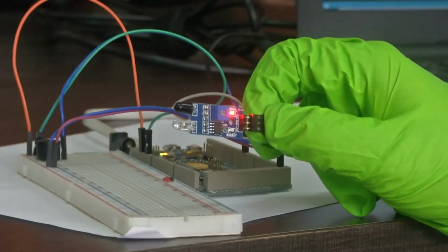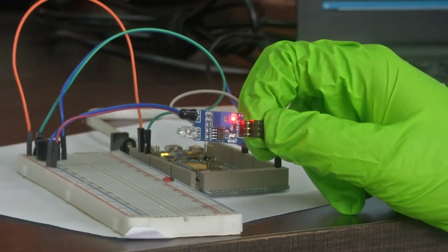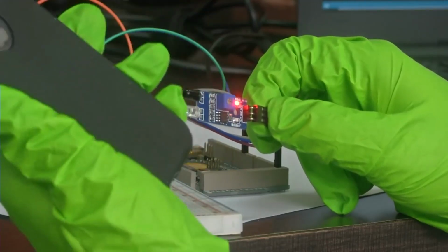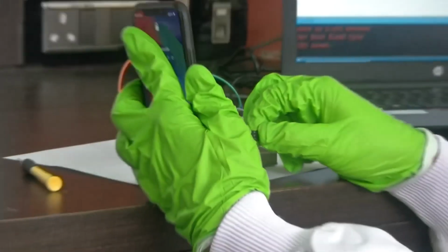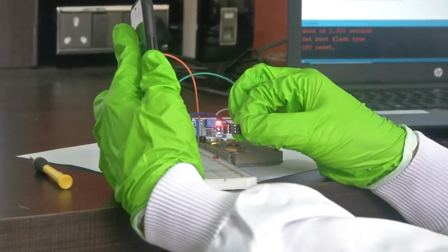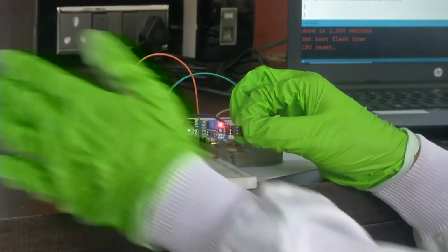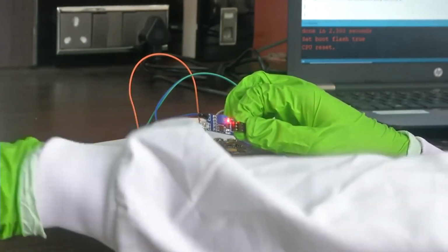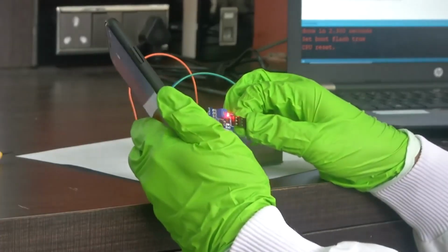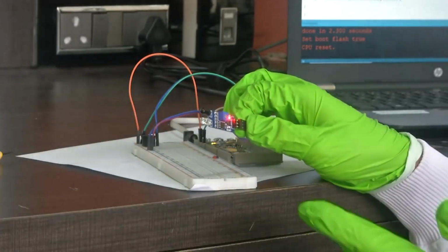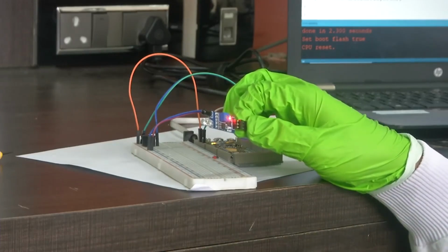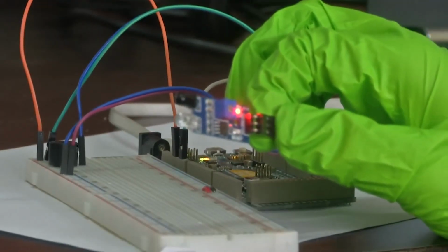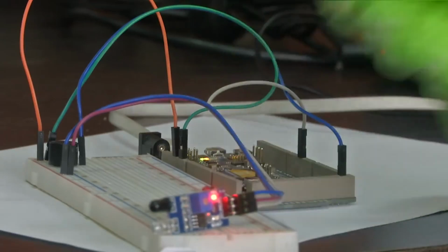Okay, and one more example I have to show is, I told you the color of the object also is important. So I have a black phone over here. Okay, the surface is black now. If I show it here, it's not detecting because the black surface is not reflecting. The green gloves I am using are still reflecting, and the white surface here also is reflecting, but the mobile phone which is black is not reflecting. So this shows that the IR sensor can only be used when it comes to an obstacle or an object that is white or has a reflecting surface. Okay, so this is about the IR sensor.